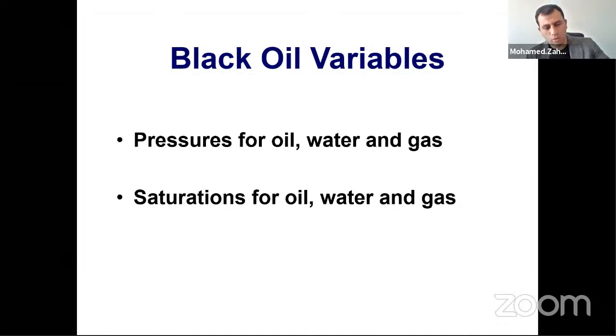How do you know that you need water flooding? If the pressure is depleted. So you need to understand how much the depletion will be. If you inject this amount of fluid, how much will the pressure be? If you inject abundant water, what does the saturation look like everywhere? Is it understood? This is what we need from the diffusivity equation: pressure and saturation.